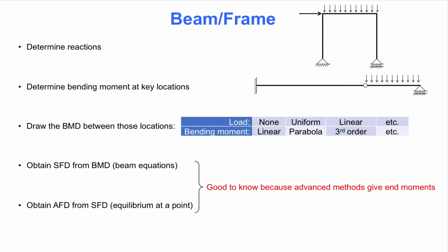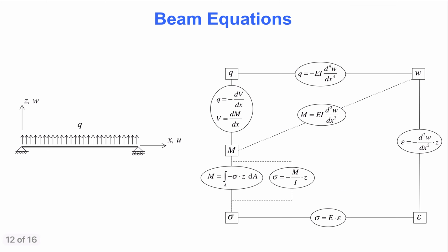Conducting structural analysis in this manner is helpful for advanced structural analysis methods, which give the end moments of the members as the primary result. However, be aware of the possibility of starting with the shear force diagram and then obtaining the bending moment diagram. The beam equations on the next slide explain the background.